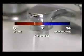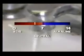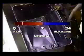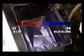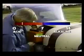Tap water is less corrosive than rainwater because rainwater has a lower pH level, which indicates a higher acid content. Salt water is even more corrosive than rain due to its high salt content, which makes it a stronger electrolyte. Moderately strong acids will severely corrode most alloys used in aircraft construction. By far, the most destructive is battery acid.